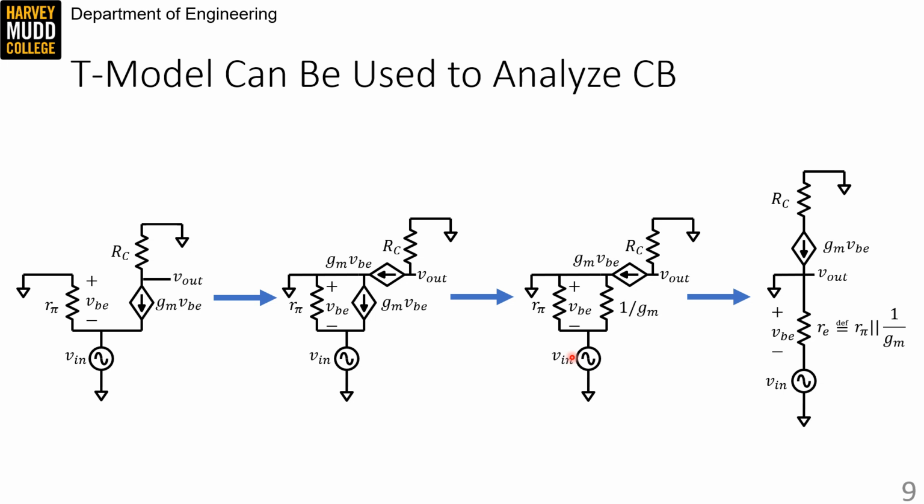So you can transform the small signal model of a common base by pretending that instead of current flowing directly from the collector to the emitter, it flows to the base and then to the emitter. And we're allowed to do this because our models only capture the terminal behavior of transistors. They don't discuss what's going on internally, so as long as we have the same current coming out of the same terminals, any set of elements that we choose to draw inside of them is fine.